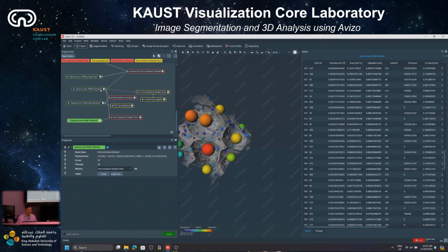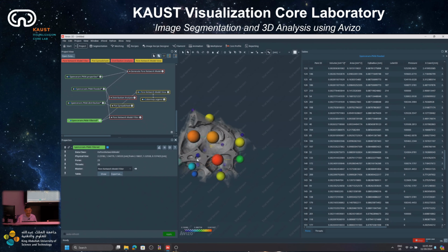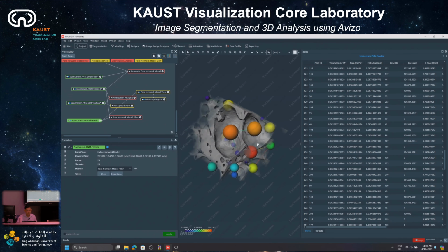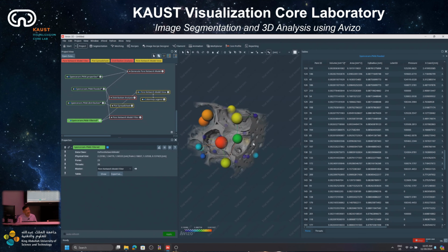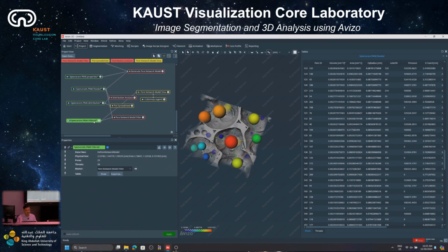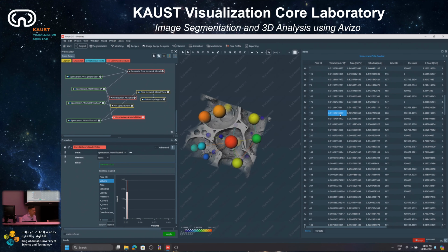You can use the same Pore network model view to view the new pore. You can see that it's been filtered based on the size. The smaller size pore has been removed, and only the larger pore that's larger than this one remains. So as you can see, I just filtered them based on the pore size that are larger than this value, because you can see here the distribution of the pore size.